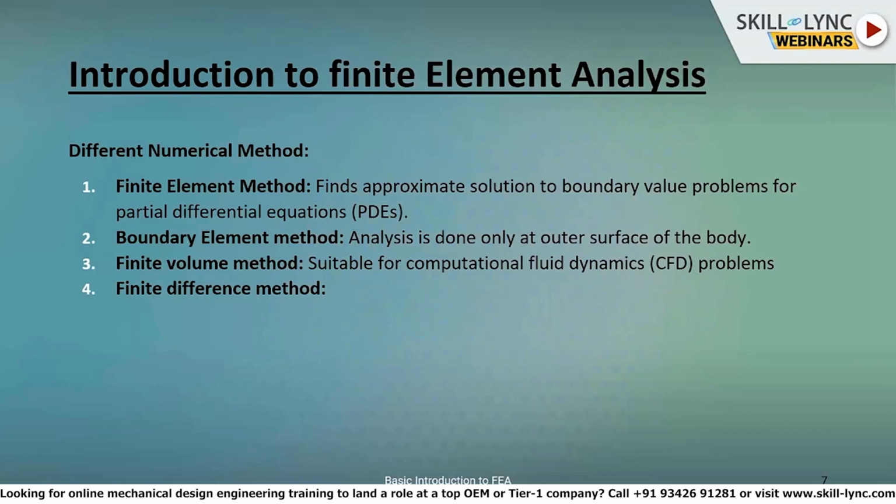So the finite element method, which basically depends on solving the partial differential equation, is the best method out of all these four, which can give you the most accurate results. That's why the finite element method is so widely used in the industry. So for fluid dynamics problems, we use FVM, that is finite volume method, and for structural and thermal related problems, we go with the finite element method, as those are the methods which will give you the best results for any mechanical problem.